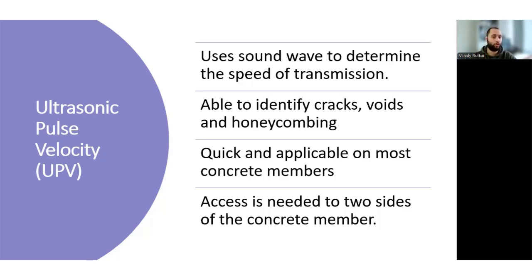This method is especially useful for detecting internal defects within columns, and I've actually used this to great success on a critical infrastructure project where the adequacy of a number of columns was questioned due to visible voiding on all adjacent columns which had to be knocked down. These additional columns simply could not be knocked down, as there had already been too much of a delay, and knocking them down would have delayed the project by 3 to 4 weeks.